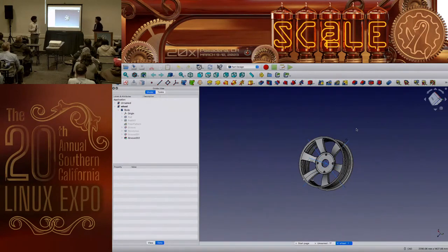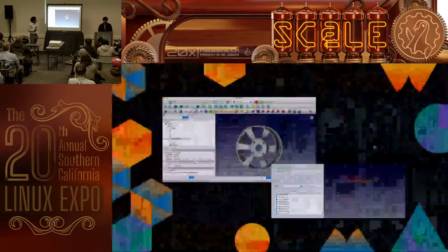After that, I simply had to make one of these spokes. There are 6 spokes, and I only made one of them. But using the Part Design toolset, I was able to select polar pattern. I don't know if you can read it, but over there it says polar pattern. That let me copy one sketch and create it multiple times. So that's what I did for that.